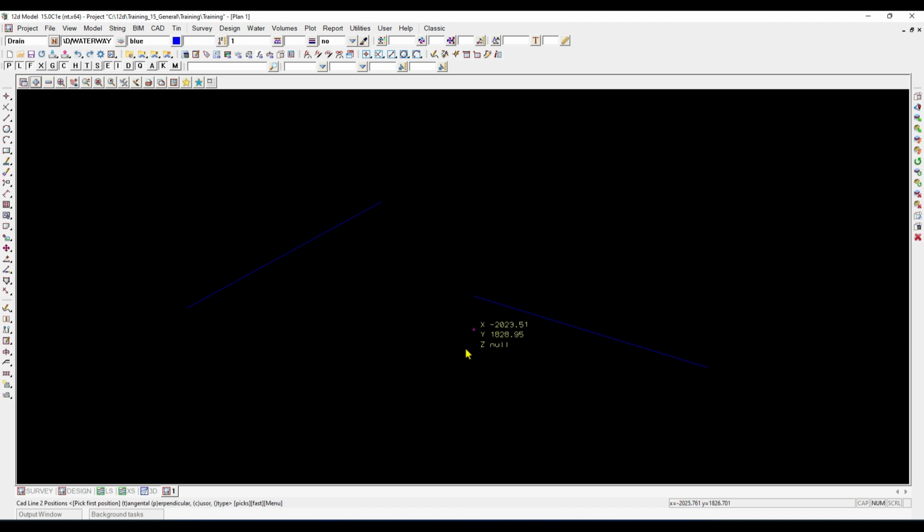So the fast accept, you don't need to select using the left mouse button. Where you're happy with it, you just press down on your middle mouse button and it will fast accept. I do recommend that you get very comfortable with 12D before you start using fast accepts, because there is a bit of a trick to it. So anywhere where something is able to be fast accepted, when you click the middle mouse button, it will be selected. But there is a hierarchy to what gets selected, and where that position ends up.